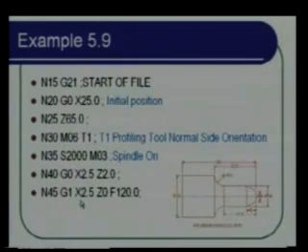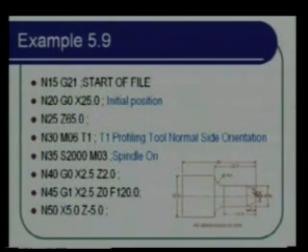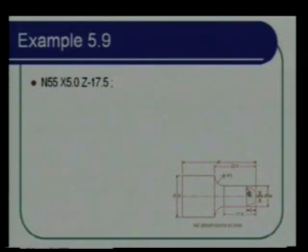So that's why from here we are touching with G1, and then specify the feed rate. So the tool will actually be touching at this point, and then from there you move the tool along in this direction, X5, Z minus 5 for this. Then from there, from X5 you go to Z minus 17.5, because the same X is there, but along the Z direction you are going.